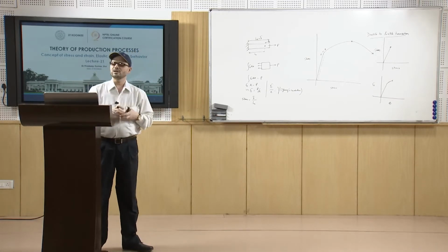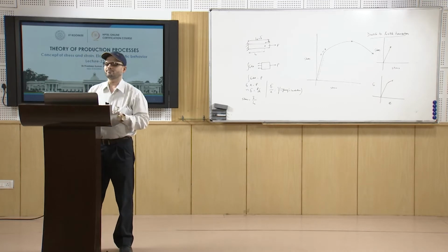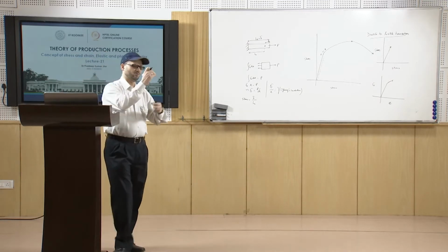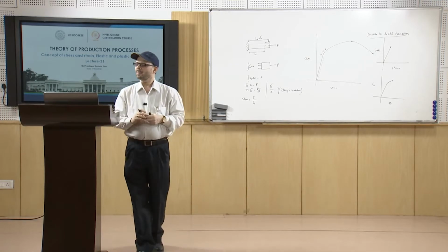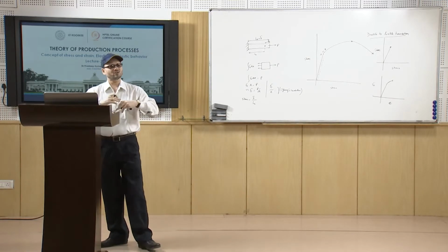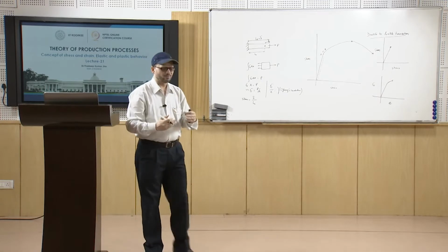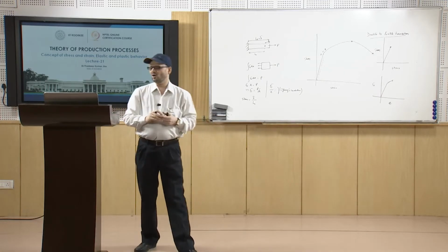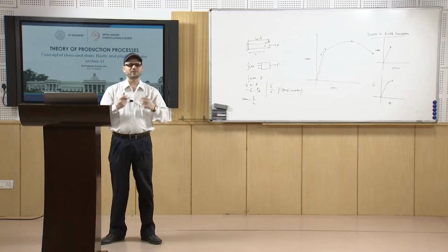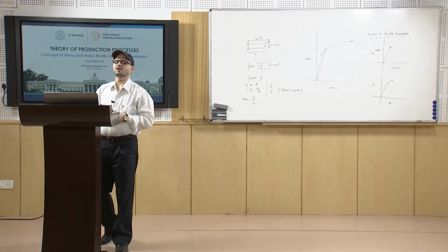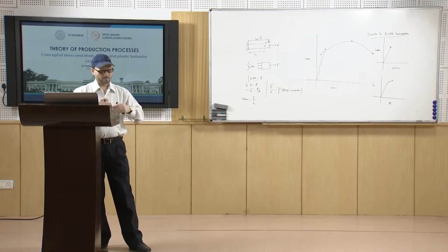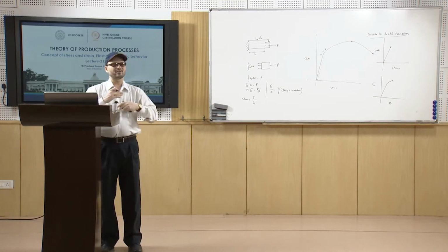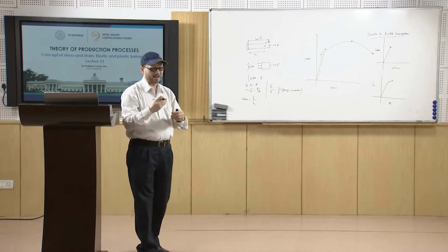Because what happens is that you have a deflection of a beam which is maximum under a certain load. So, that way it will not be suitable for further use, or you may sometimes have the buckling of certain slender columns where the load actually surpasses the Euler critical load.